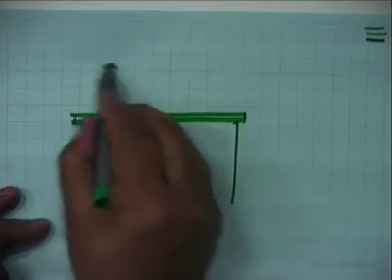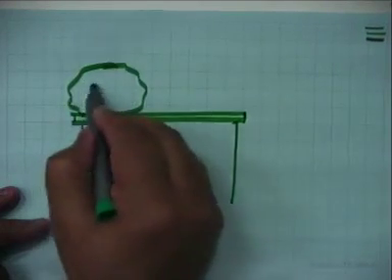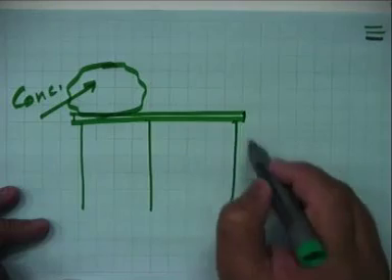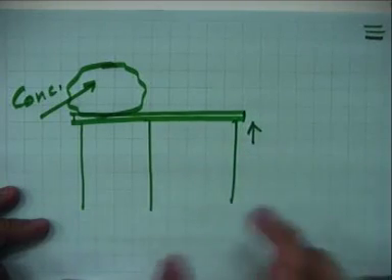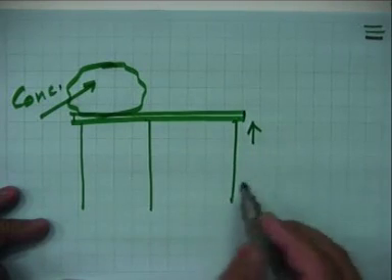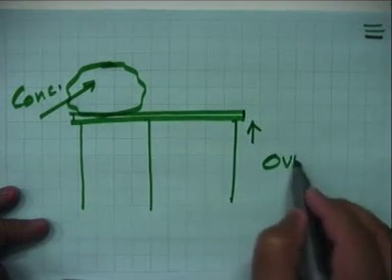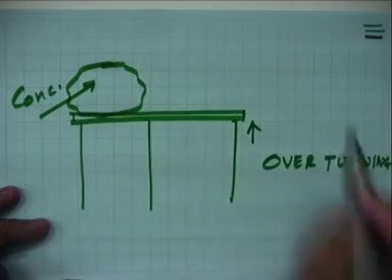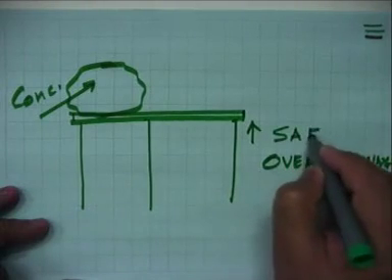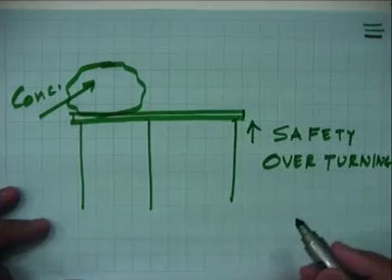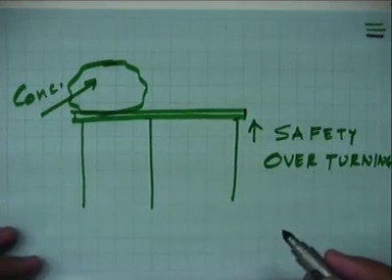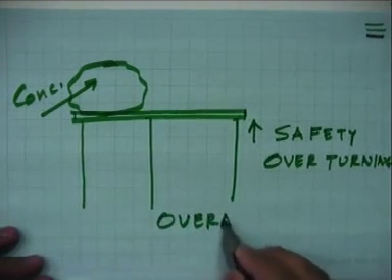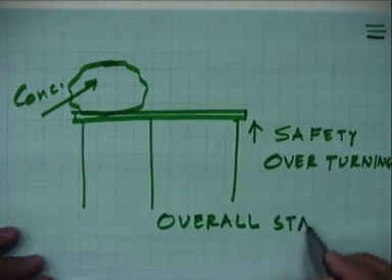Now, when you, let us say, apply very heavy load, very large amount of concrete here, you may find that this support may get lifted up. So, your formwork must be safe against overturning also. So, the first parameter is safety. Your formwork must be safe. It should carry all the loads safely. Then you should also ensure the overall stability.